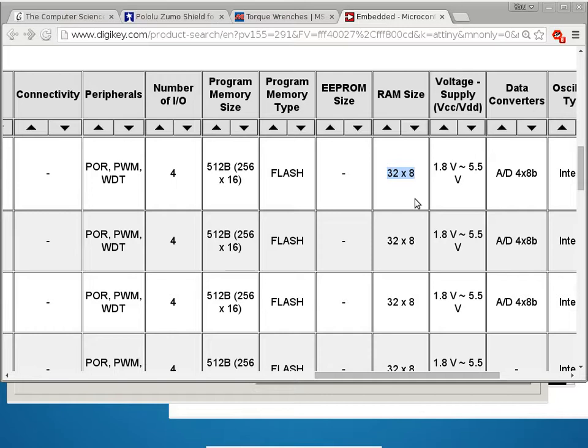So what you're paying in terms of price for an inexpensive small device is development cost. Because you cannot just write a program in C++ or worse, Java, and expect it to run here. You have to hand code in assembly programming language for these devices in order to fit as much logic in it as possible. C can run on that? Not this particular model. There are other AVRs where you can run C programs, but not this one. In order for C to run, you need about 2 kilobytes or so to run comfortably, and this one only has 32 bytes, so that's not nearly enough.